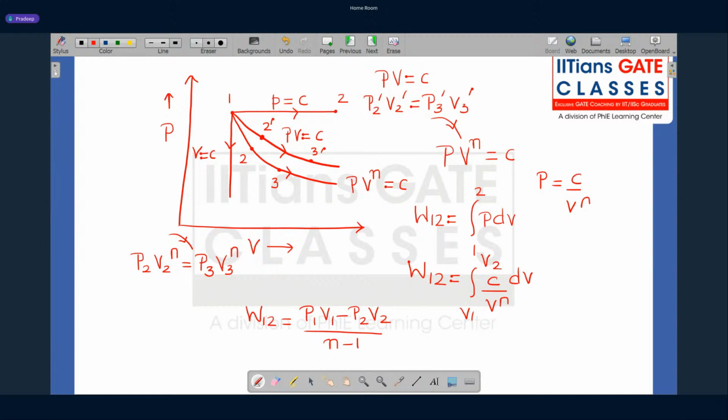So for different processes, you see you get different expressions for the work transfer. What do we understand from here? If we are talking about work transfer in thermodynamics, is work transfer dependent on the process path, or is it independent of the process path? When I figure out the work transfer for different processes, I am getting different relations.